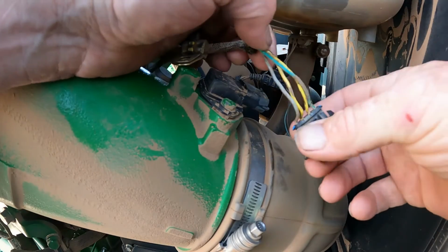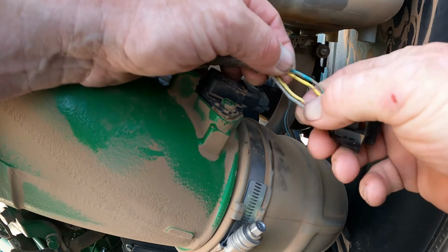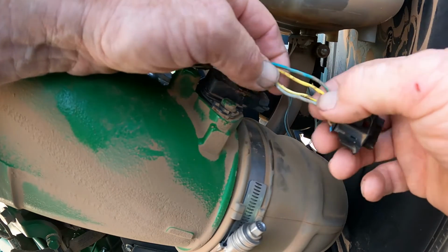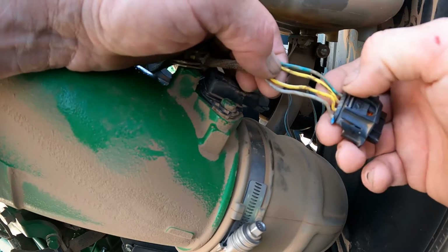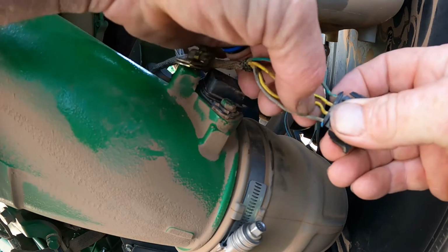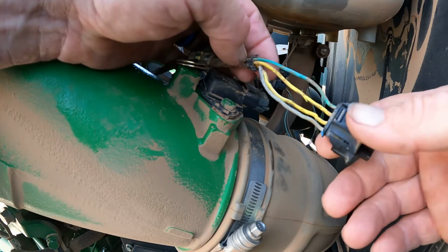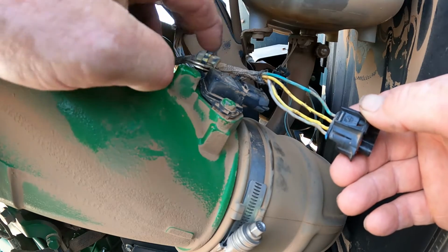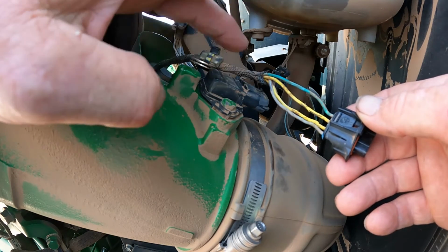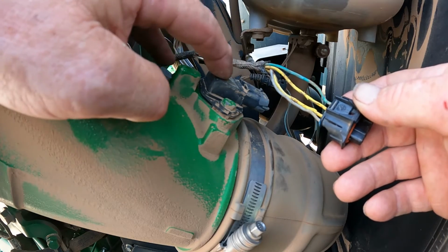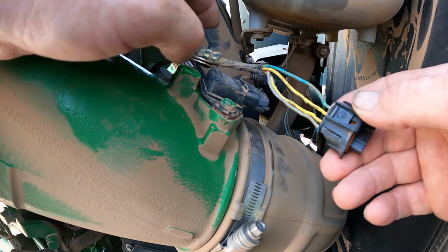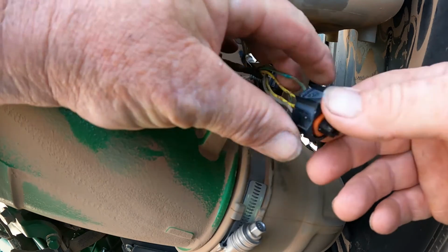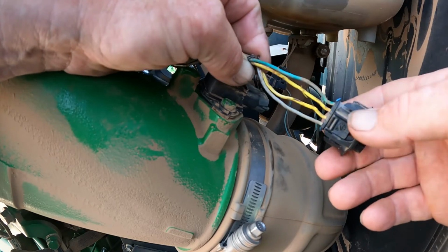And so I've got my connector here, and I've already peeled the insulation back, kind of split that open with a blade knife there, trying not to get into my wiring, okay? And I want to show you something real quick with this. I'm looking at those 4 wires, okay, and it's a CAN communication sensor, okay? And so many times I've seen a lot of people change this sensor, and it doesn't fix their problem. Okay, so I'm looking at this wiring harness. I really don't see anything wrong as far as the terminals in the end of the connector, and you really don't physically see anything wrong.